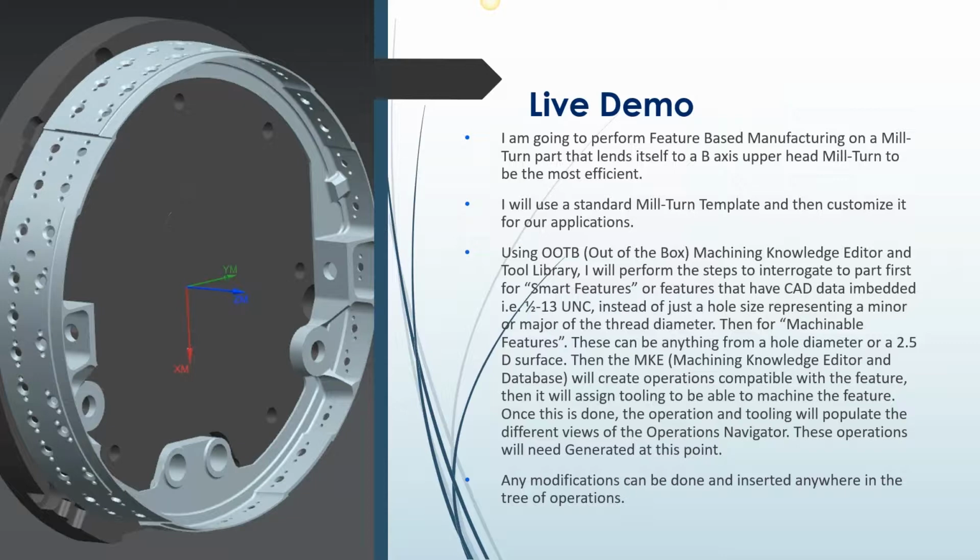Say you have a very, very large tool or large hole, say a 60 millimeter hole, it'll pull some large diameter chamfer cutter that you may not have at your shop. You can easily just change that diameter. You might possibly have to change the operation to a circle machining or a hole machining operation, so it's not doing a drilling operation, but it happens very quickly.